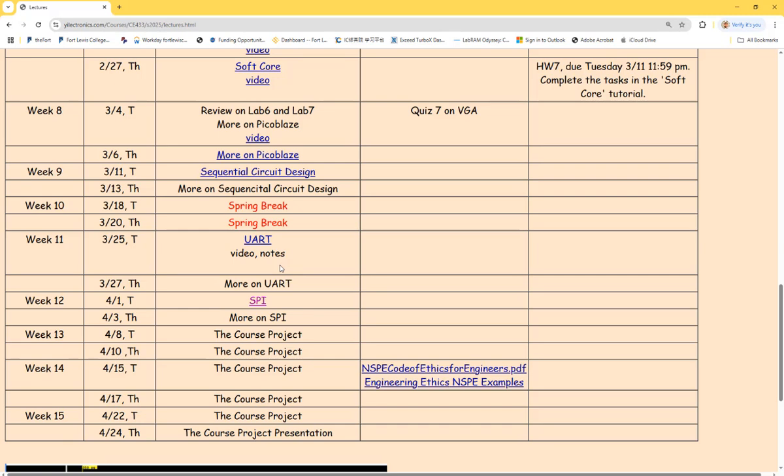In that case, I can give you multiple options. You probably have learned thermocouples in M&I, I guess. Did you? Yeah. Thermocouples are a resistance or voltage based temperature sensor, right? So depending on the voltage, you get a different temperature. So do you want to use thermocouples for this application or not? Why or why not? You wouldn't because of the long series resistance.